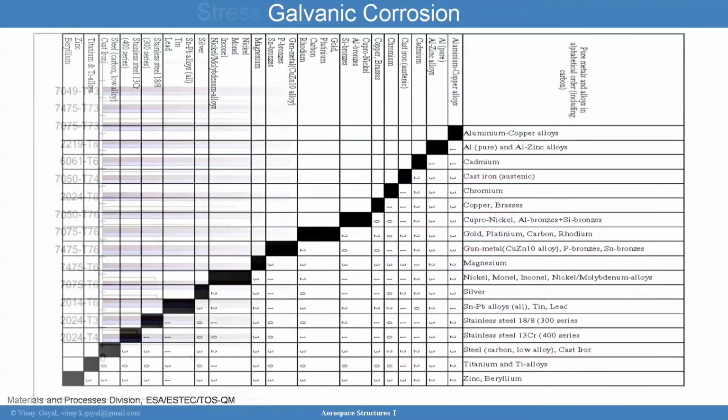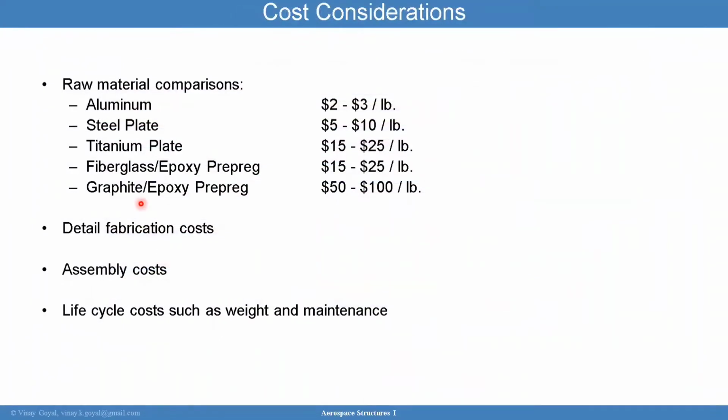And so that's how this can be useful. When you're looking at these different materials and selections, what really helps is to look at everything together and figure out the most common failure mode, which one I'm trying to avoid, and really determine what is the best fit for what you want. Low strength is not always the right answer. Sorry, high strength is not always the right answer, and low cost may not be the right answer. It could be a combination of things that allows the design to pass all these restrictions like corrosion, galvanic corrosion, compressive yield strength, and so forth.